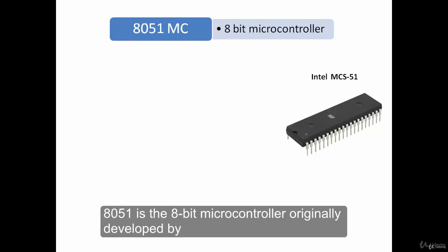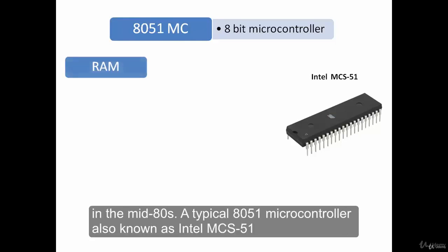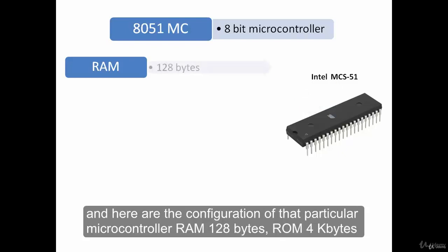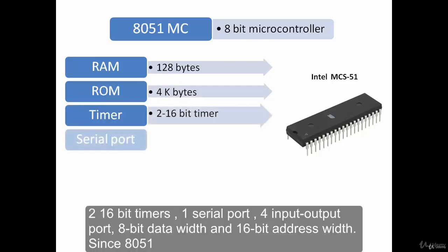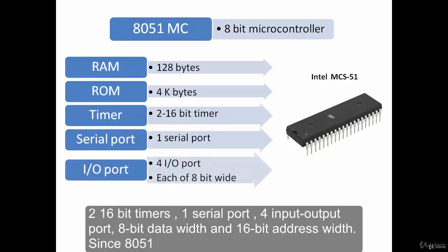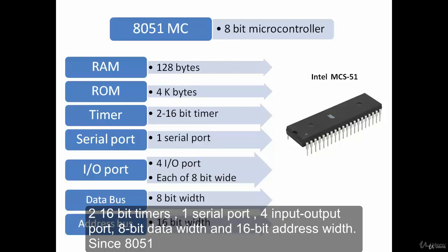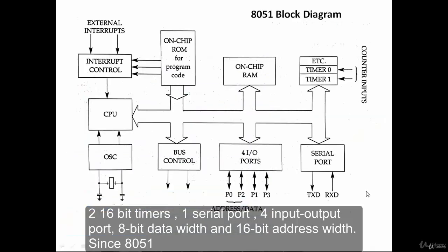8051 is an 8-bit microcontroller originally developed by Intel in the mid-80s. A typical 8051 microcontroller, also known as Intel MCS-51, has the following configuration: RAM 128 bytes, ROM 4 kilobytes, two 16-bit timers, one serial port, 4 input-output ports, 8-bit data width, and 16-bit address width.